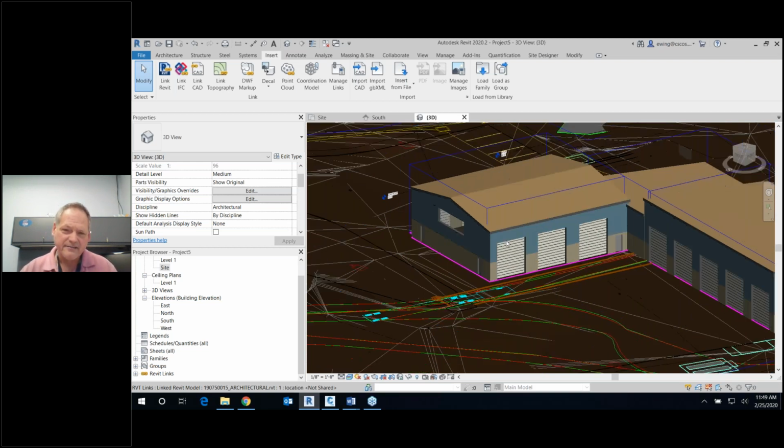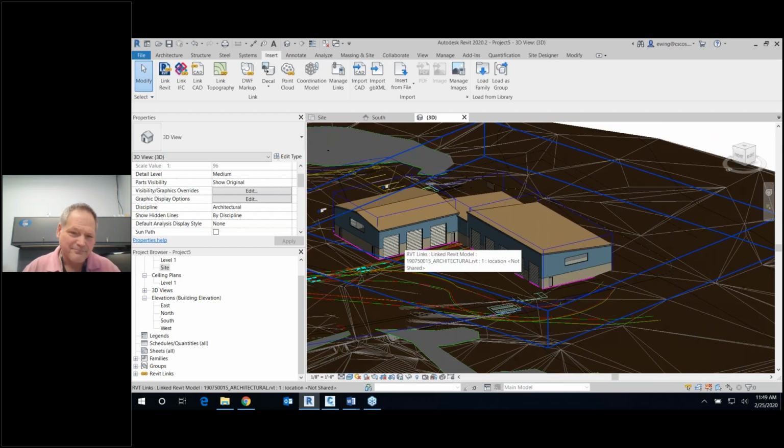On a project this size, it's a bus maintenance facility, this is not one of the big projects I worry about. And I wouldn't mind not even having a site model on this project. But on projects where we're going to have multiple trades and multiple people in each model, you want to rethink how much stuff you're bringing into that native architectural model, right? Because you're going to have all the trades linked, because you have to have the drawing sheets. You start to have a lot of data in that model that maybe doesn't have to be there.